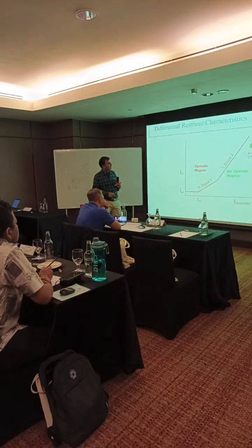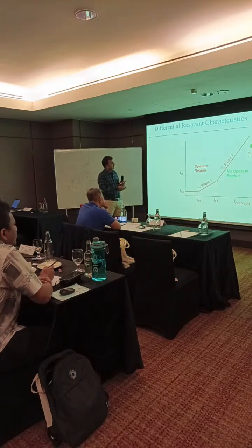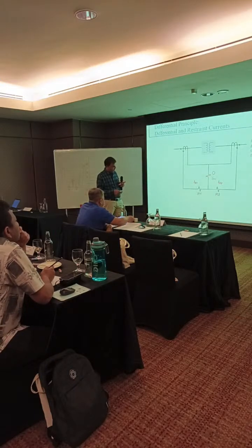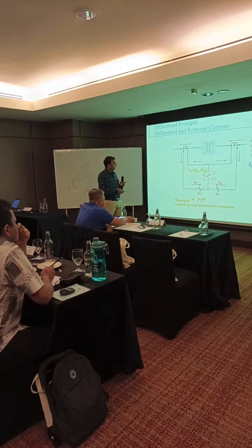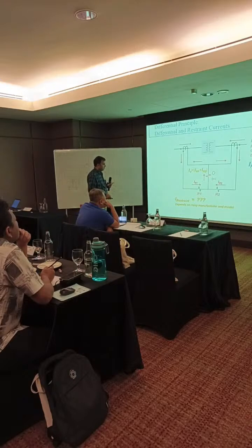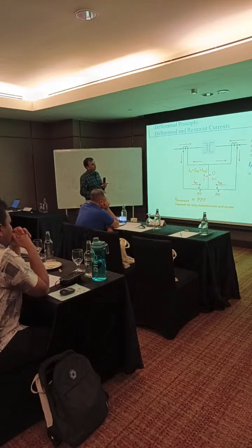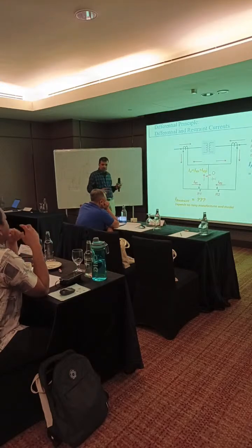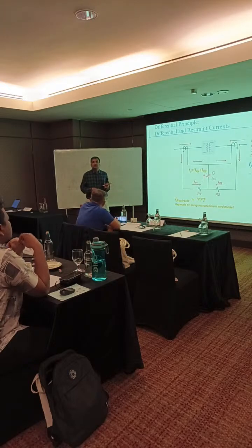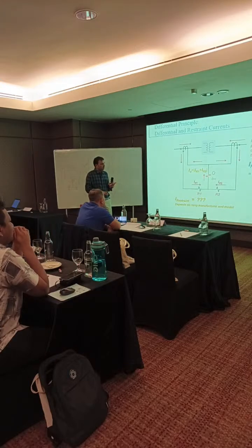Okay, so this is already done. The differential restraint characteristic we already covered. There are different formulas; it depends on the manufacturer. We discussed it yesterday. This IR1 plus IR2, like we calculated for the Siemens relay as well as the SEL relay yesterday, is the same formula.